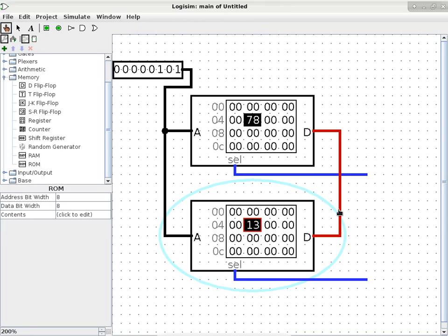Depending on the value of the resistor, let's say this is R, the amount of current flowing through here is I, the voltage differential divided by R. This R is typically in the range of, I would say, probably 1 ohm or something like that. So you're dividing 1.8 volts by 1 ohm, which is 1.8 amps.